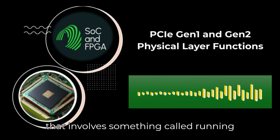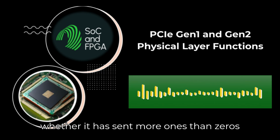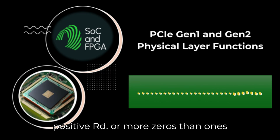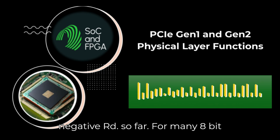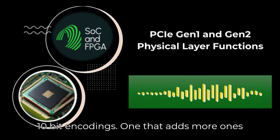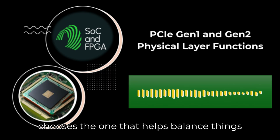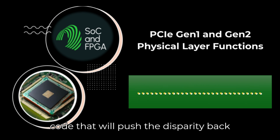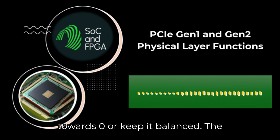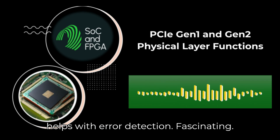That involves something called running disparity, RD. The encoder keeps track of whether it has sent more ones than zeros, positive RD, or more zeros than ones, negative RD, so far. For many 8-bit inputs, there are actually two possible 10-bit encodings, one that adds more ones and one that adds more zeros. So it chooses the one that helps balance things out. Precisely. Based on the current running disparity, it picks the 10-bit code that will push the disparity back towards 0 or keep it balanced. The receiver tracks this RD too, which also helps with error detection.